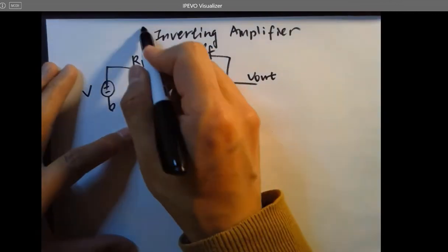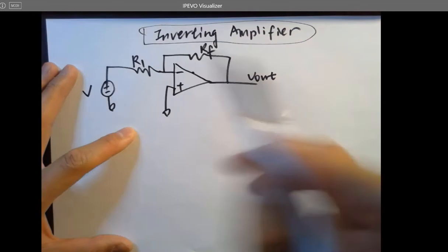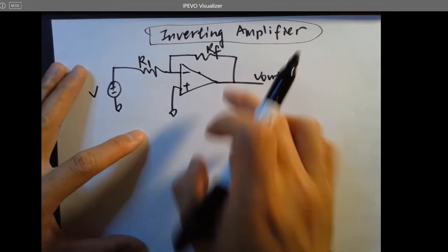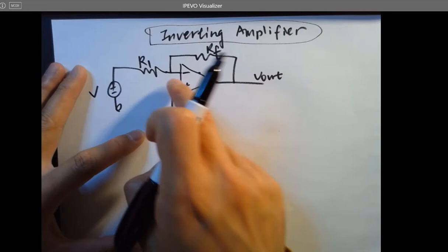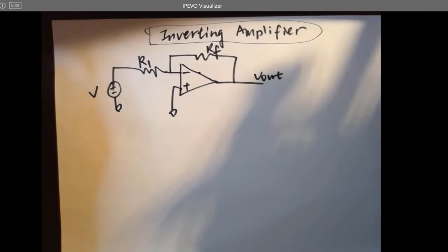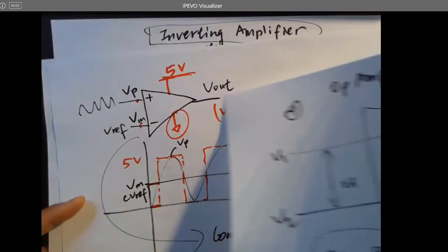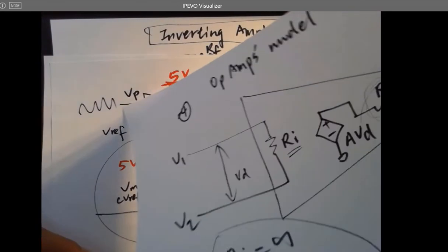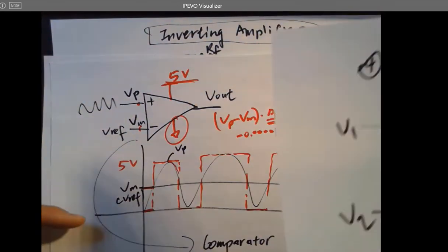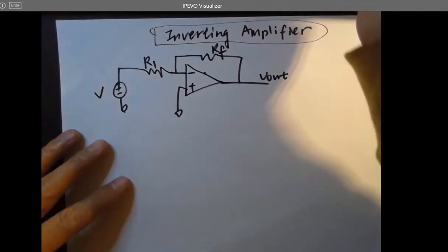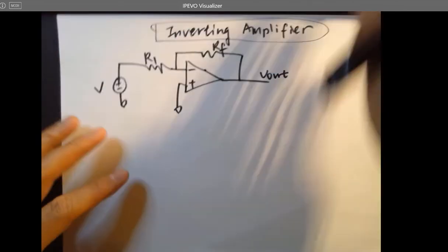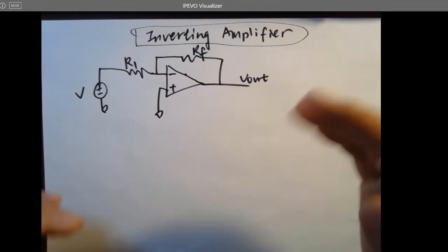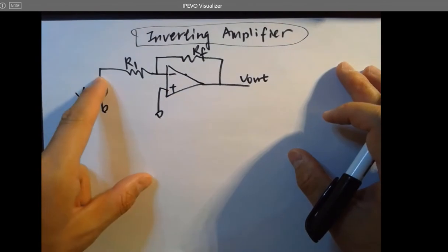There are several properties for this structure. The reason we need a feedback resistor here, compared to the open loop configuration where nothing is connected between VL and the input terminals, is because we want to form a reasonable gain to amplify the voltage.